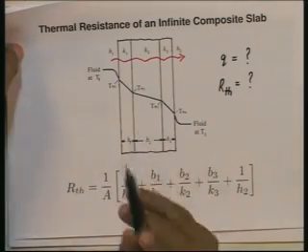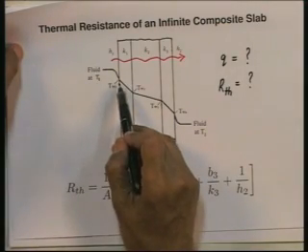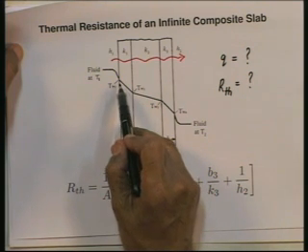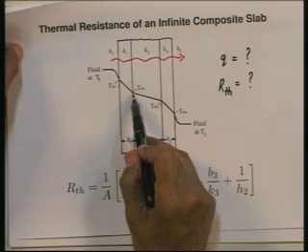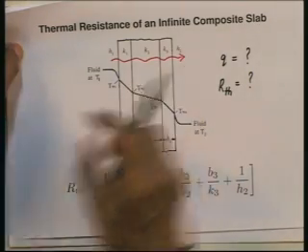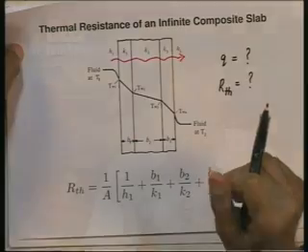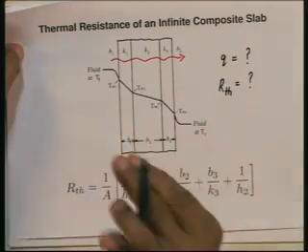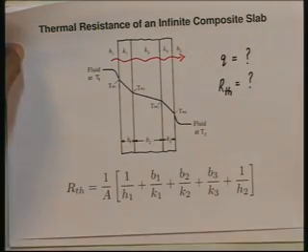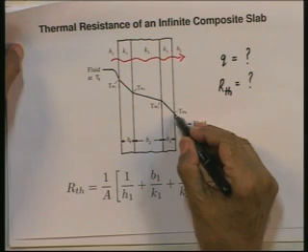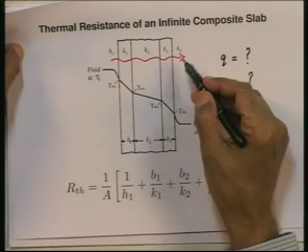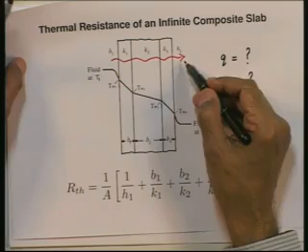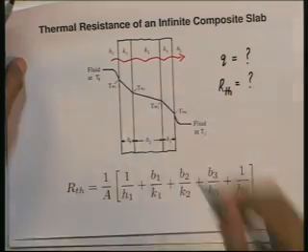Across the first thermal resistance, there is a temperature difference T1 minus TW1, which is governed by Newton's law of cooling. Across the next one, TW1 minus TW2, I can use the result for an infinite slab which I derived a few minutes ago. Same for the second and the third slab, I can use the linear distribution and the heat flow rate result which I got a moment ago. And finally, for the last thermal resistance where there is a heat transfer coefficient H2, I can use Newton's law of cooling to put down the expression for heat flow rate. So, let us do that.